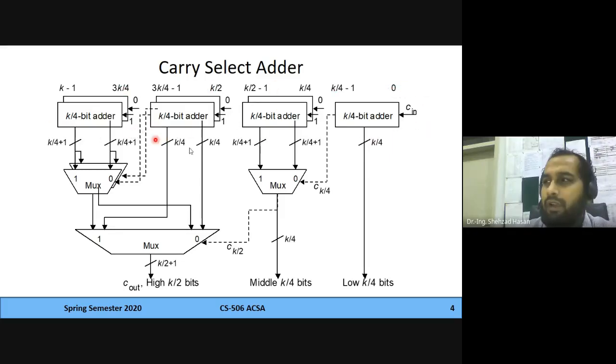So nothing more. Plus there is one level of multiplexer over here, another level of multiplexer over here, right? So you have 8 plus 1 plus 1. So the same 32-bit number can now be done in 10 steps, in 10 units of time, right? So it can be 10 maximum units of time for a 32-bit number.